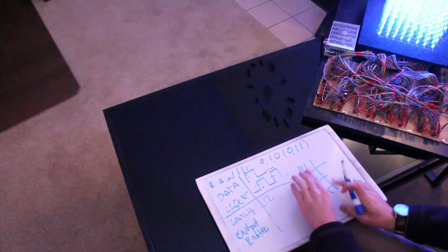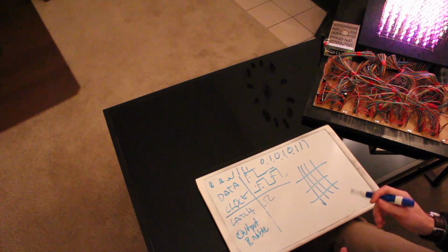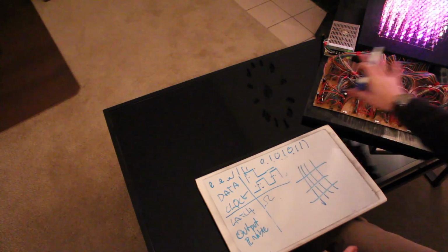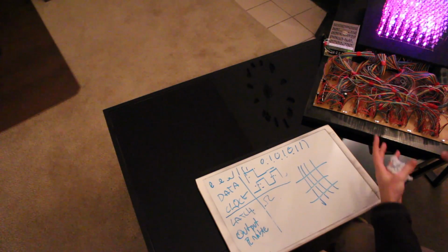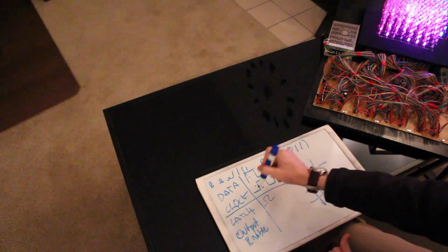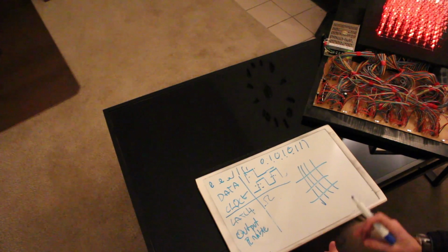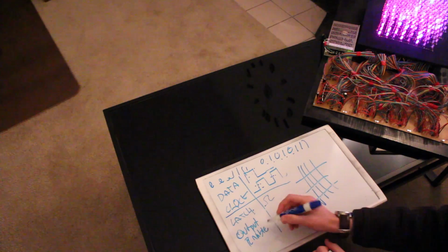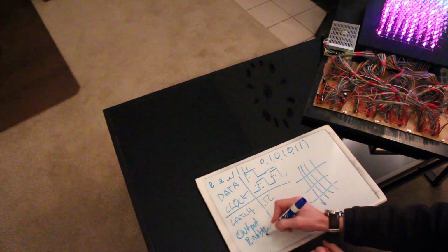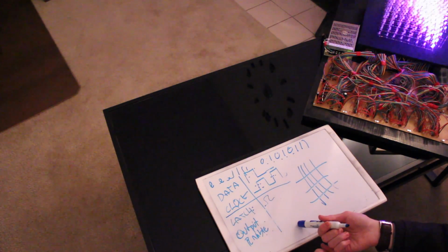So these shift registers are controlling both of them, and there are delays all over the place with this, and you're getting into a weird realm of physics when you talk about this LED cube, because there's just so much wire and so much data. This clock and data line are clocking at 8 megahertz, so it's pretty fast stuff. It's so fast that what I decided to do is just toggle this pin right before I latch, and then enable everybody right after.